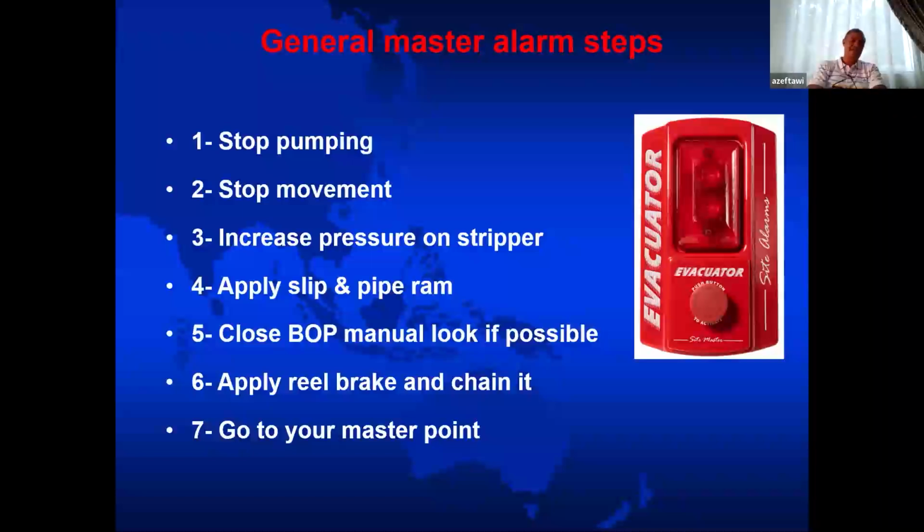While you're staying at the master point for 30 minutes, your engine is running. This is ABC. You cannot stop the engine. But the engine creates vibration. This vibration affects the drum. So you're going to see the drum moves like that. A little bit of movement like that. This will make the wraps, even if they are tight wraps, fine, it will make them loose.